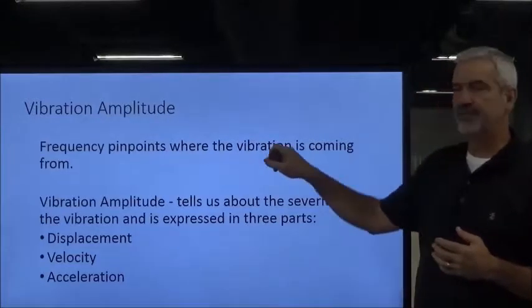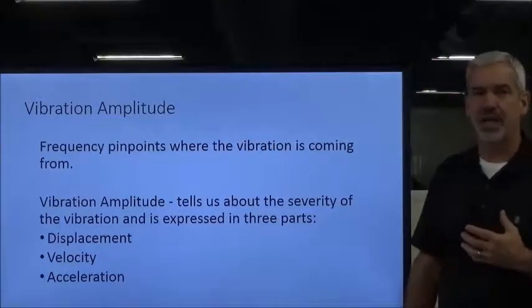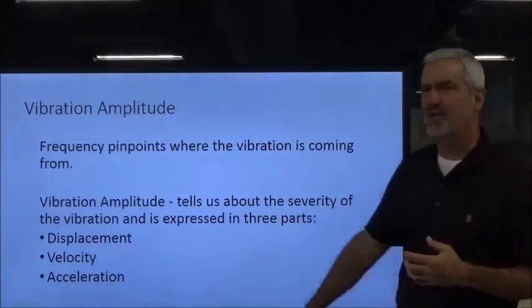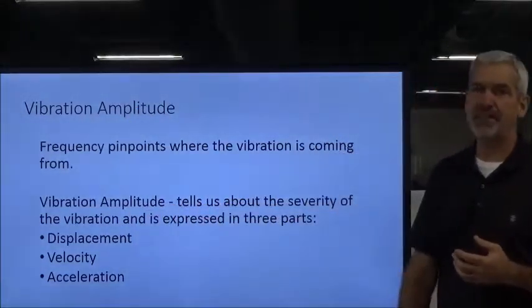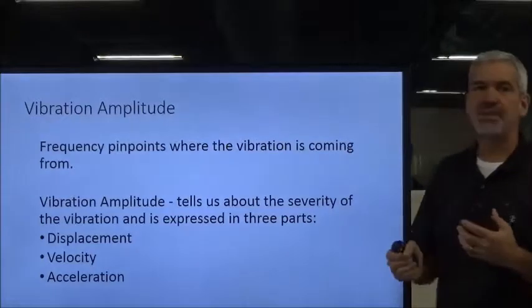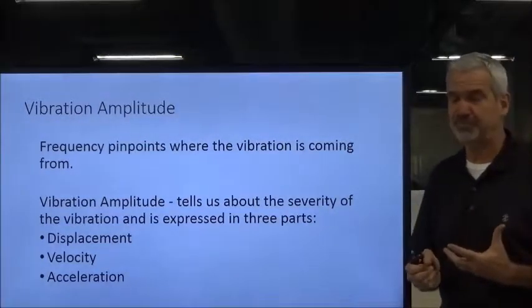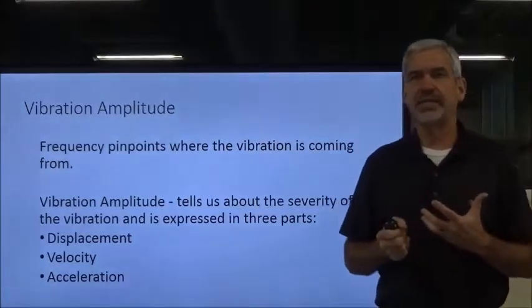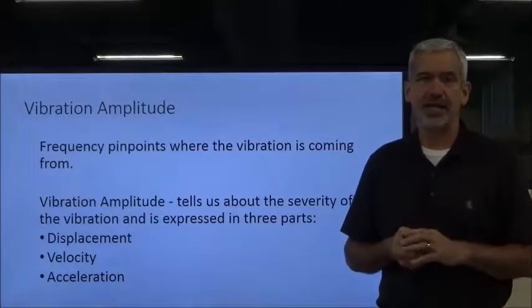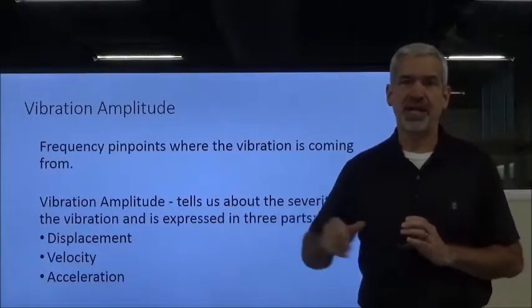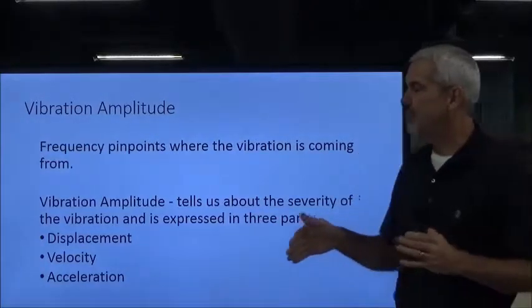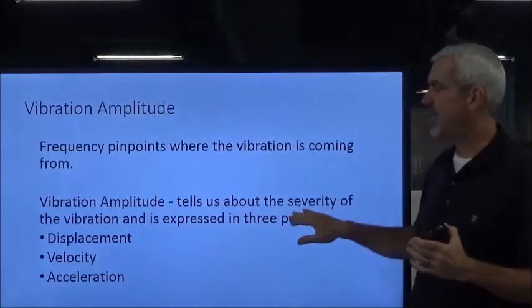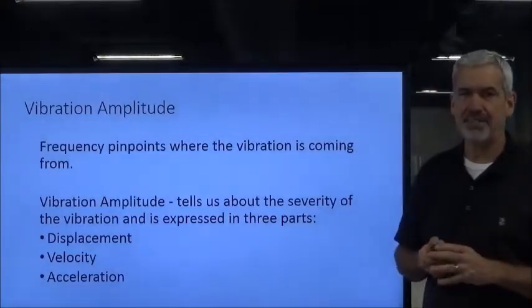Okay, like I said, frequency pinpoints the vibration and its source, where it's coming from. That spike that you see also tells us about vibration amplitude. This tells us about the severity of the vibration, and depending on the machine that you're looking at, that can vary from it being just fine to, oh, we've got to rebuild this or replace some components. It gives us an idea of how bad that vibration is.